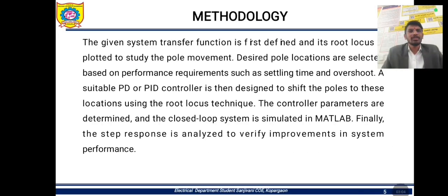So this is our methodology. For the given system transfer function, first we define the root locus plot to study pole movement. Desired pole locations are selected based on performance requirements such as settling time and overshoot. A suitable PD or PID controller is then designed to shift the poles to this location using the root locus technique.